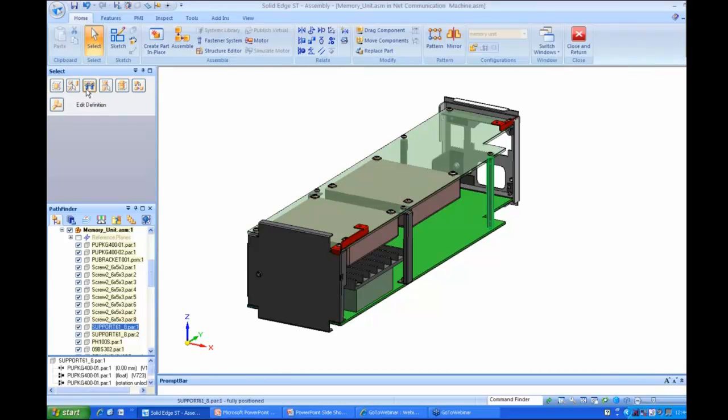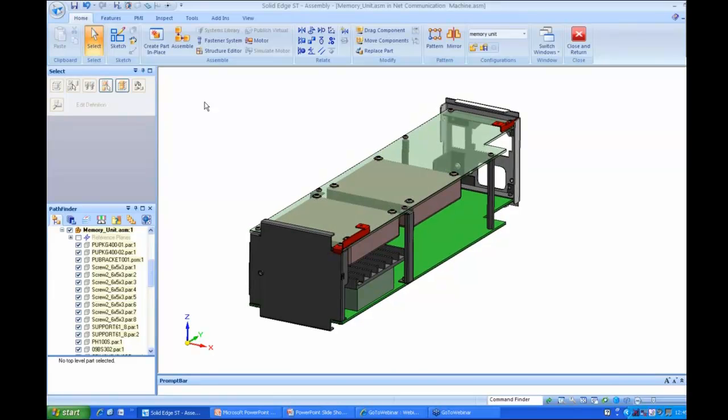Let's go back to the original. I have tools that can select subassembly parts, so if they match other identical occurrences in the selected subassembly, I can grab those. I can select small parts, so if I'm wanting to hide a bunch of my fasteners, with small parts you see part size, think of this as a slider bar. As I increase the number, it's going to start highlighting larger and larger parts. You can see that those fasteners are already highlighted. Now brackets are starting to turn green with the selection, and I can use that as my select set. So I just wanted to point out some of those tools to help us select parts.